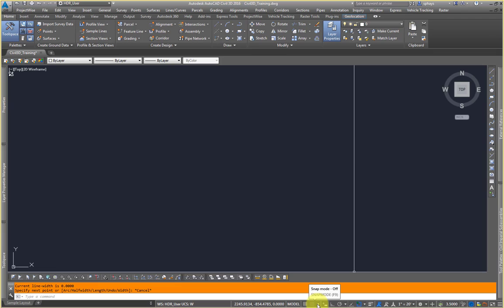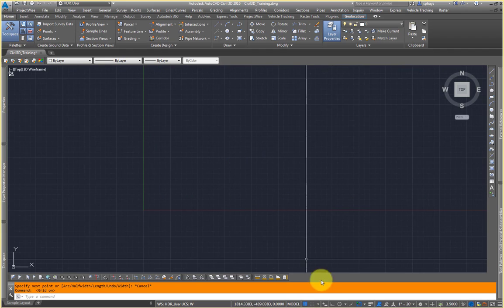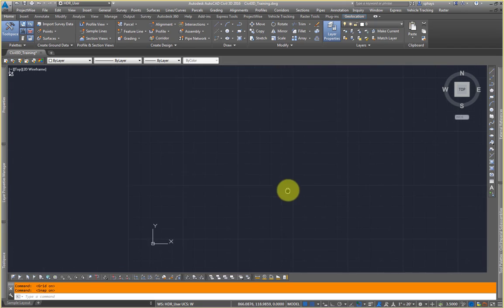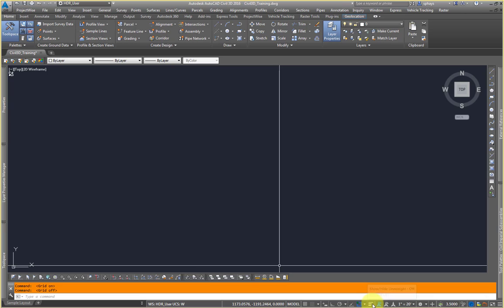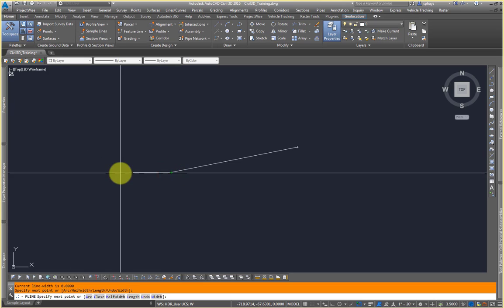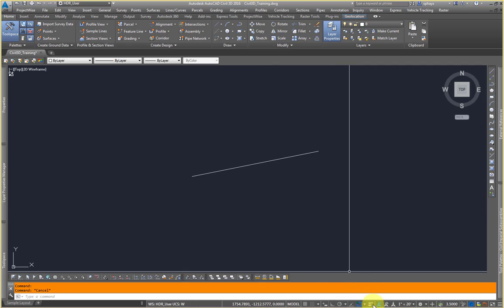Let's see. So snap mode, I forget what snap mode is. Grid mode, oh yeah, sorry, grid mode turns on a grid, and then snap mode turns it on so it actually will snap. I believe it snaps to these grids here. Then we also have line weight display. I'm sure you guys can guess, if your object has a thick line weight, it does not get displayed until you go down and click this guy. Okay, so all your line weights are turned off until you have that guy checked.